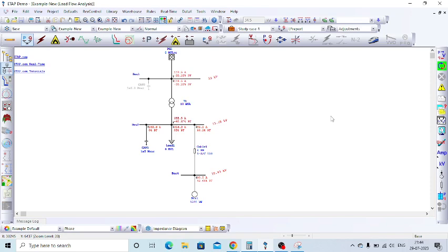So due to the capacitor bank, then maintenance costs, etc., and also the return on investment. Sorry, corresponding to the energy loss. For example, if I am installing the capacitor bank, then I am saving some amount of energy in the distribution feeder. If I am not installing the capacitor bank, the energy loss is high. If I am installing the capacitor bank, the energy loss is low.